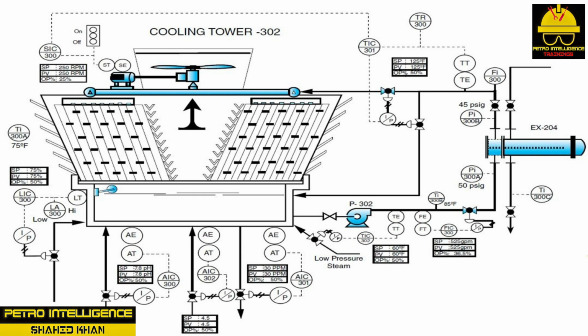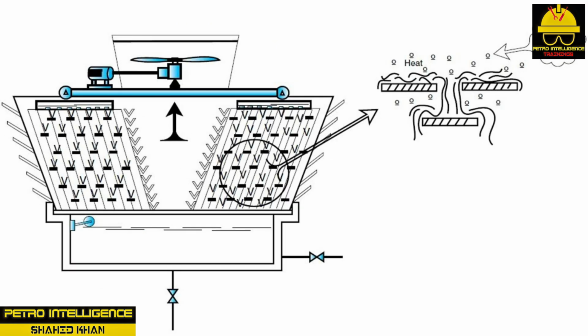Fill provides a vastly expanded surface area interface that enhances air-liquid contact. As evaporation occurs, the air becomes saturated with water and is carried out of the cooling tower system. The fill is comprised of pressure-treated materials, wooden slats, run through a plastic support structure. The fill is designed to provide plenty of surface area so good air-liquid contact is ensured.